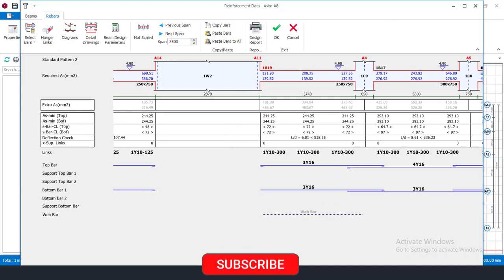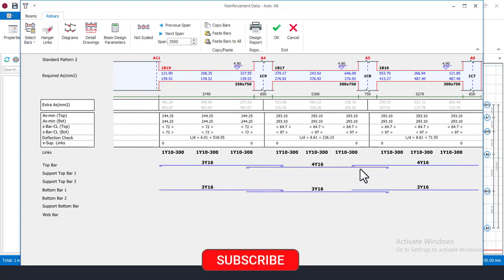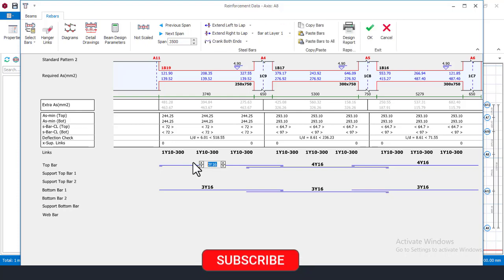So right now, just to have a smooth sail of my reinforcement during the construction, here giving me 4 number of 16, and this one giving me 3. And just to have a smooth placing of reinforcement during the construction, I will come here right now and make it to be 4. But basically 3 was okay for that, but just to have a smooth sail, I'll make it to be 4. Okay, and I'll come here right now again. I can choose to make it 3, but just to avoid confusion at sites, I make it 4 because this place is very small compared to these other panels here. So just to have a smooth lane of your bars and to avoid much cutting, I mean, let me just carry the same bar length and then flow all the way down here. Okay, that's fine. So right now, at the bottom, everything looks okay.